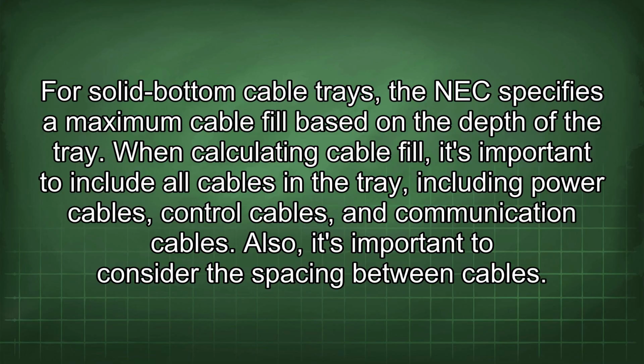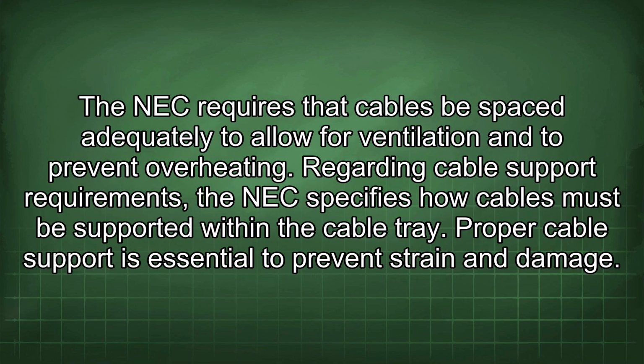When calculating cable fill, it's important to include all cables in the tray, including power cables, control cables, and communication cables. Also, it's important to consider the spacing between cables. The NEC requires that cables be spaced adequately to allow for ventilation and to prevent overheating. Regarding cable support requirements, the NEC specifies how cables must be supported within the cable tray.